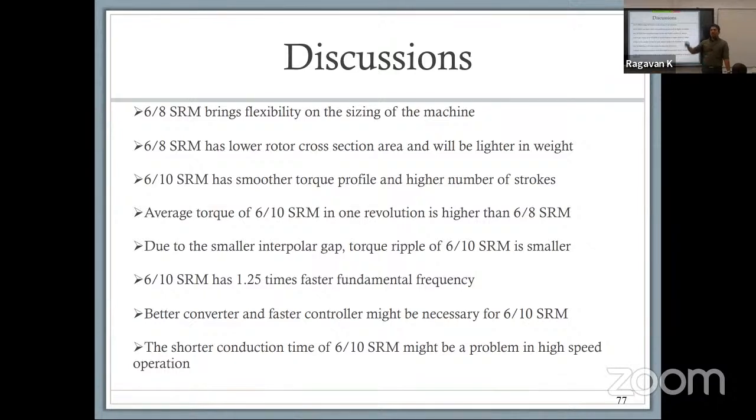What that means is that my sampling, my processing, all has to happen faster. I did shift, not the stress, but I did shift the complexity from the machine to the converter, with the understanding that my converter can handle a lot more than a motor. My motor has real physical constraints. I only have so much volume. Torque ripple is a function of the motor output.